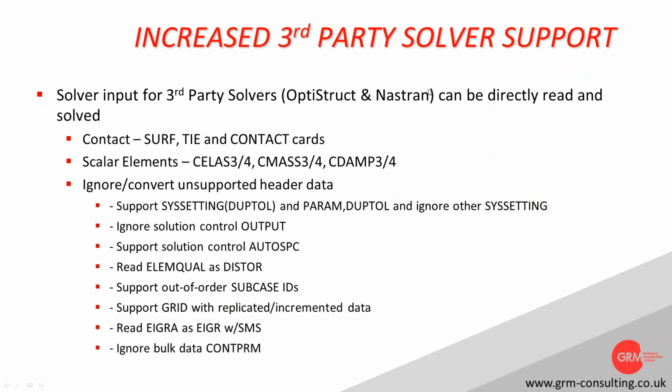These are pressures, and that's just something to make you aware of as you're running it. Okay, so in terms of the enhanced support, there are some very specific additions to the input file support to allow users of Nastran and OptiStruct to run their models directly. If you pass a lot of the input data cards you see on screen now, these will be internally converted into Genesis data format in a pre-processing step, allowing you to run the model directly without the need of editing header, subcase and executive control data, and some of the alternative formats for scalar elements and contact and so on.